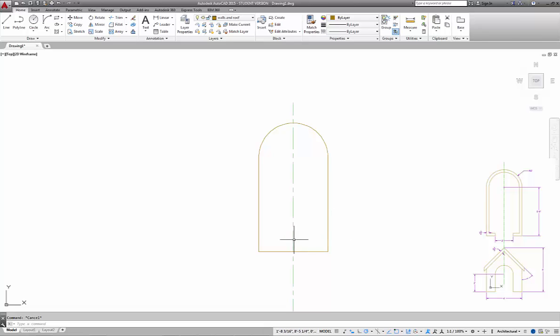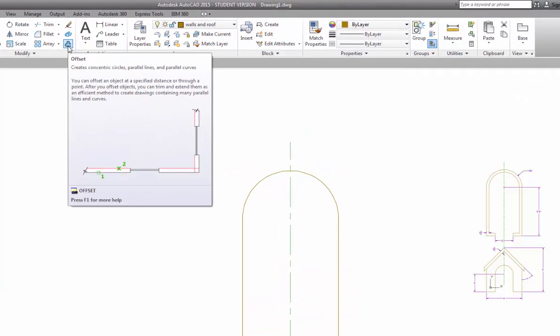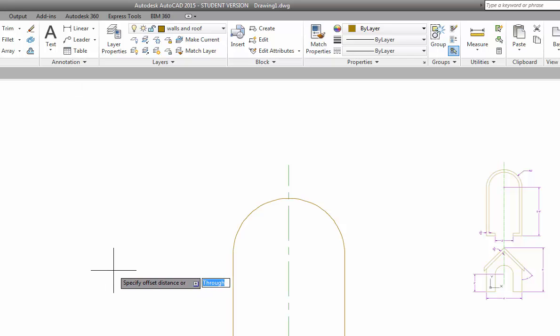All right. So we've got an opening here in the front that's 2 foot wide. Right now, we basically have a closed house. Let's do the walls first, and then we'll do the opening. So to create the walls that are 3.5 inches thick, because we're actually doing a serious doghouse here, the one that will protect the dog through anything. 3.5 inches. Isn't that 3.5 also? Absolutely. So even though it's an architecture, I can type in decimal-based drawing units. So 3.5 inches is 3.5 inches.